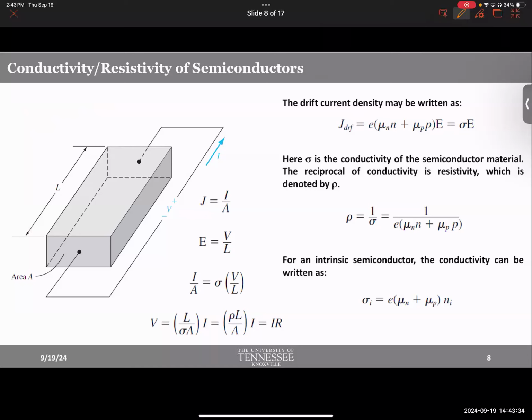Apparently, Ohm's law should be written, as I told you in the last class, not in the form of V equals IR. More fundamentally, it should be written as, so let's go from V equals IR. Let me write it in a way that you have 1 over R times V. What is the inverse of resistance? Conductance. All right. So remember, this is conductance. So instead of writing current, I should have written current density. Instead of dealing with voltage, I should have dealt with electric field.